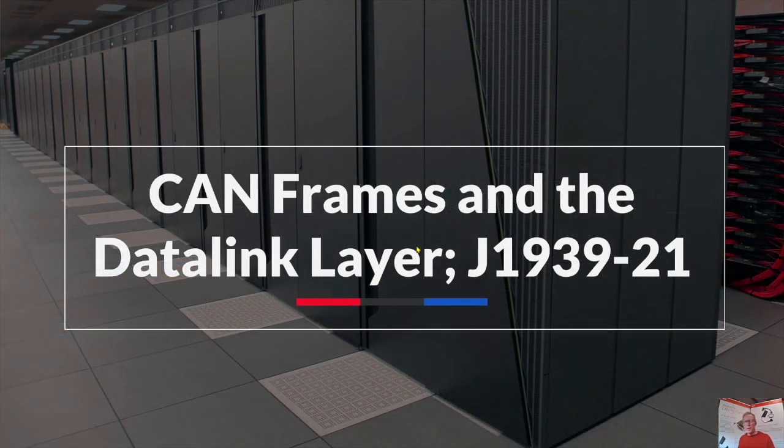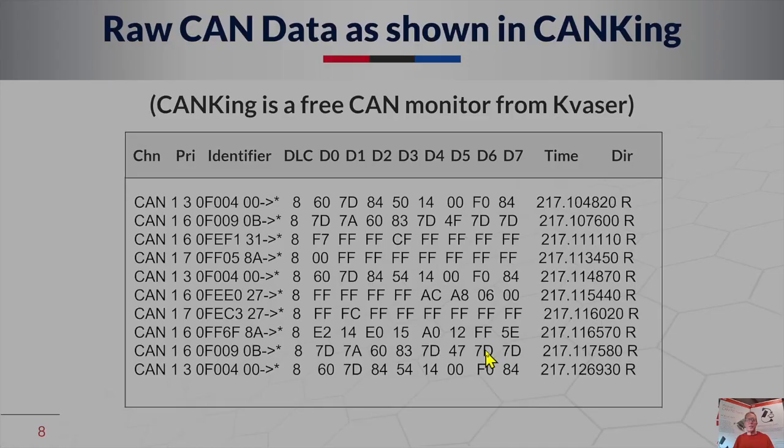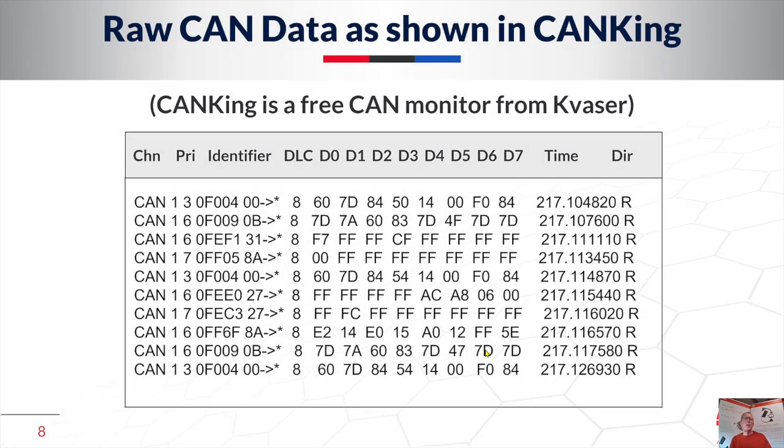So, CAN frames and -21, the classic CAN data link definitions. Here I'm just showing some basic CAN data as captured by CANKing, a free bus monitor for raw CAN data and DBC file functionality, downloadable from the Kvaser.com website. It's a good application for raw data.